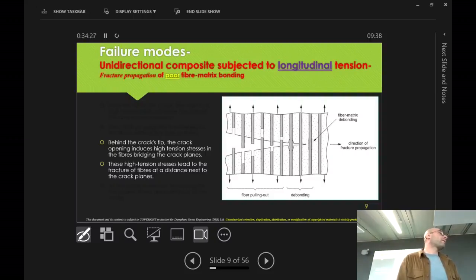Debonding is the main mechanism of failure, even on the first one, and then after that the fibers break away randomly. Debonding is one of them, but it doesn't happen in isolation. No, but I mean that then causes the other ones. That's why all the fibers are breaking randomly. To be perfectly honest, from my experience of doing all these tests, the first thing that happens is the matrix cracking. Yeah, no, sorry, I'm just asking why it's so uneven where the fibers break.